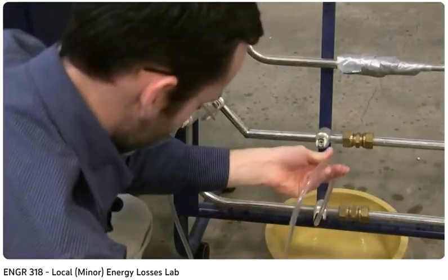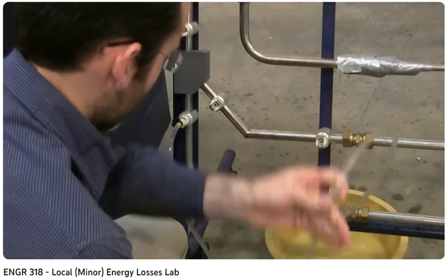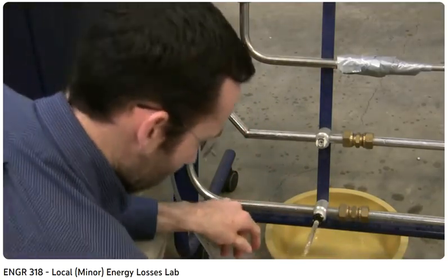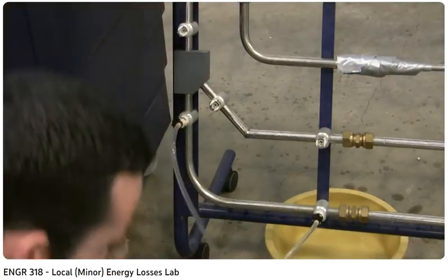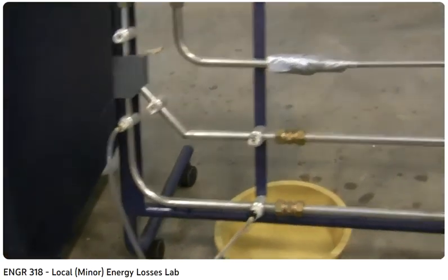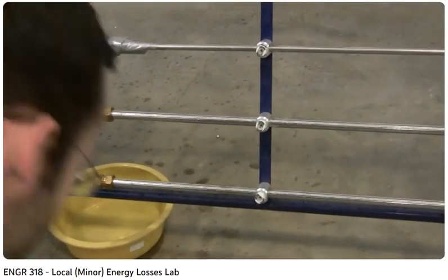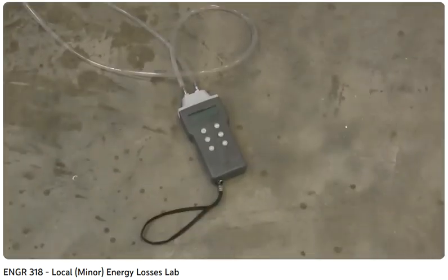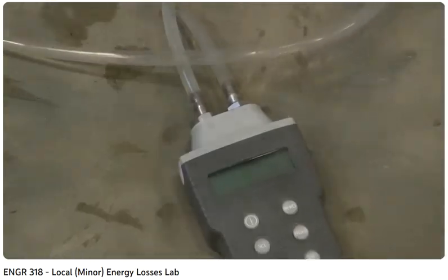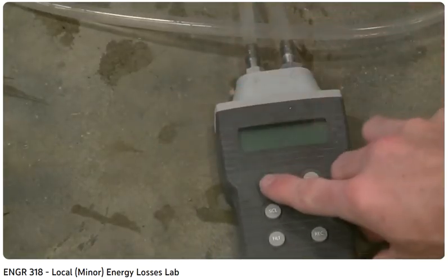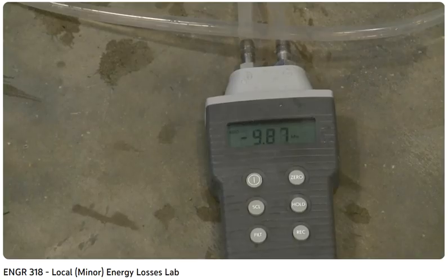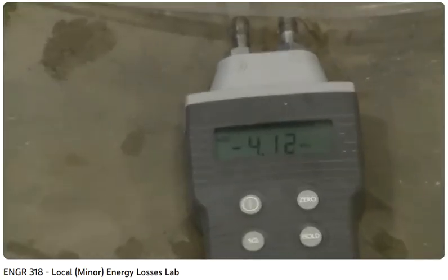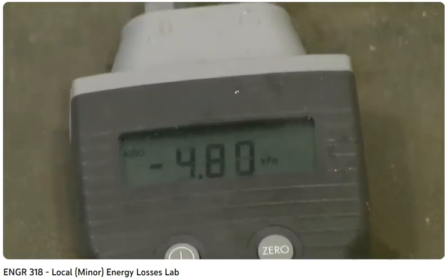All right. I'll inspect to see if there's any air in the lines, and it seems like I didn't get any air in the lines, so I'm in good shape there. Let's again get some pressure measurements. I'm going to mop up a little bit more of this overspray, particularly off the pressure instrument. All right, let's take a look at some of the data that we're getting through this device. Seems like we're losing a little bit more pressure through here than we did through the other one.